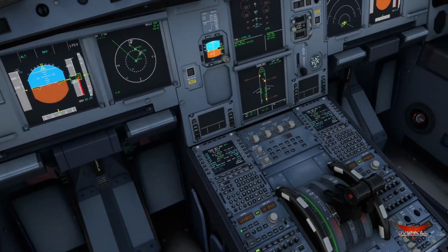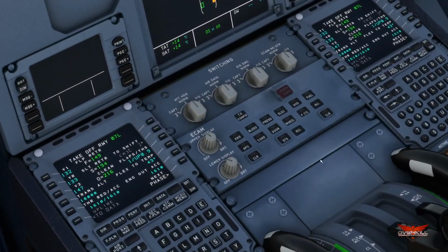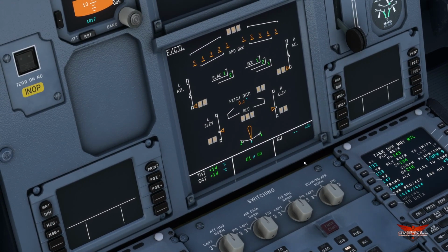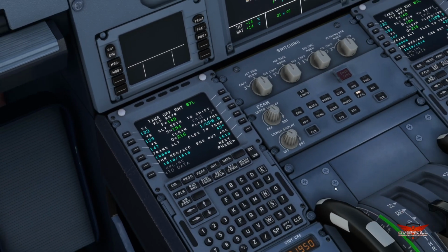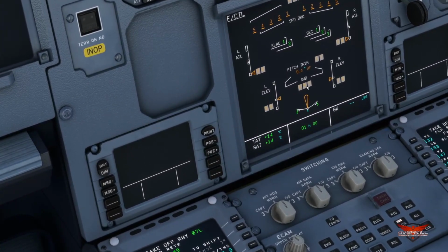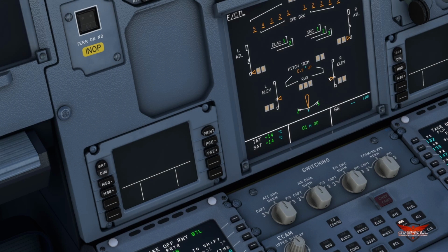All right, so now we need to set our trim. What we're going to do with that trim setting now is come here and go to the flight control surfaces. And let's see here. Where is our trim setting? There's our pitch trim right here. We're going to roll the trim wheel back until we see 0.9 up. And there it is right there, 0.9 degrees up.